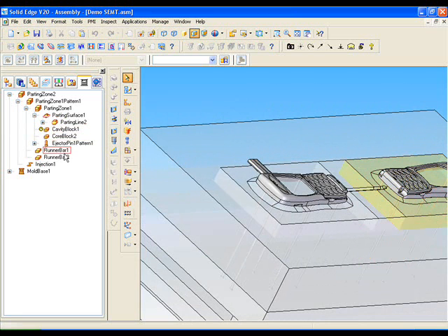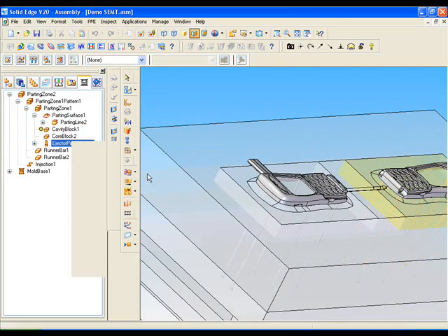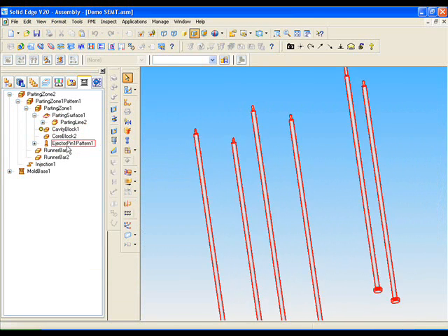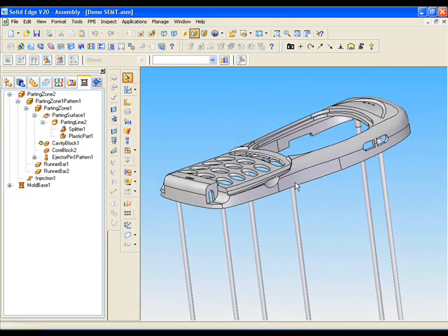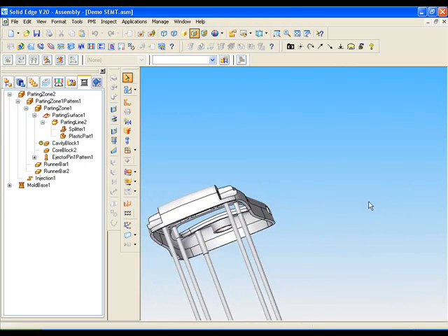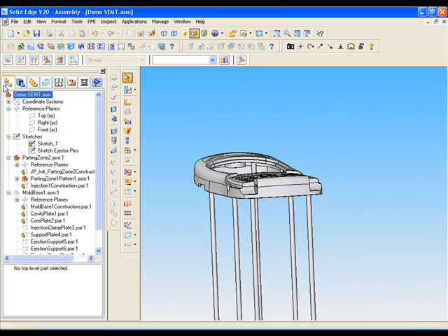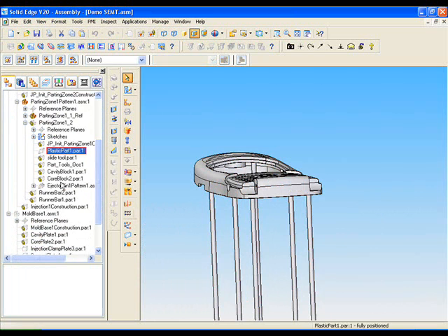Check that the ejector pin pattern entry was added in the mold tooling edge bar below the parting zone, indicating the dependencies. Also check that the ejector pins were trimmed by the parting surface. The details in the part where the ejector pins touch are now clear. As the sketch to position the ejector pins was created by including edges of the part itself, if a change is made on the part, it's propagated to the associated sketch and, therefore, to the ejector pins pattern.